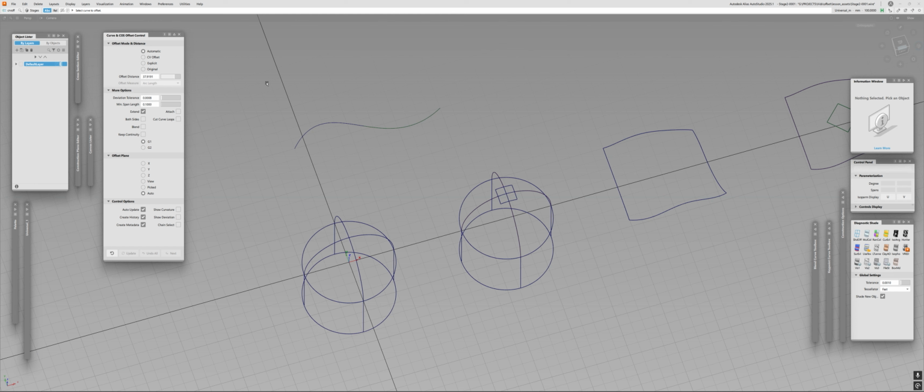That said, the offset command is a basis for all thickening commands, and in Alias specifically, the offset command is the only way to give thickness properly. But don't be fooled by that simplicity, as the offset command in Alias is in general much more robust and gives you much more control than its solid body modeling counterparts. It can give you solids in return, yes, but it can give you much more direct control than the shell or thicken commands in solid body modeling tools.